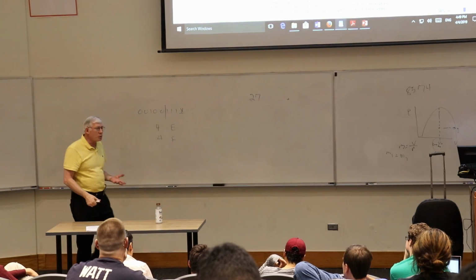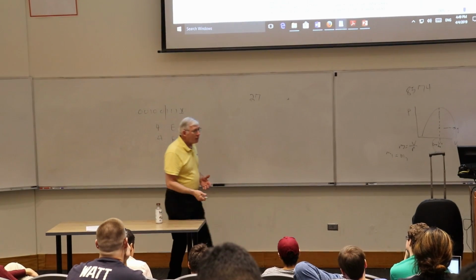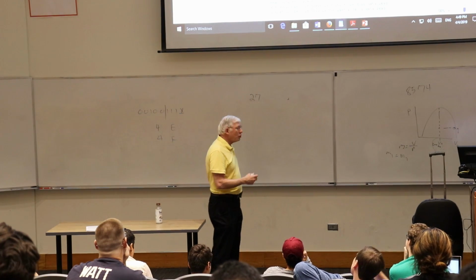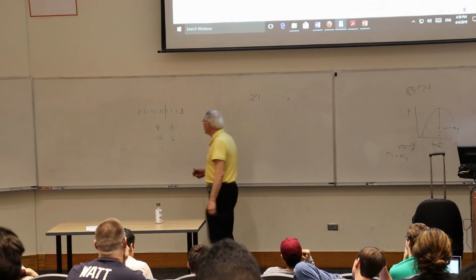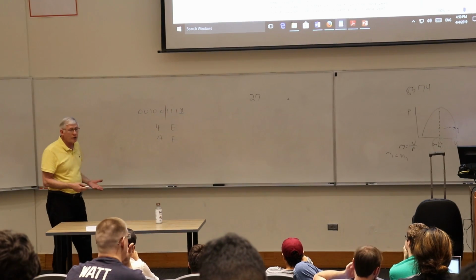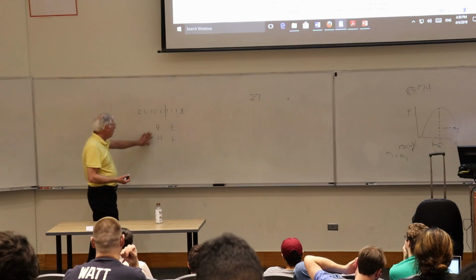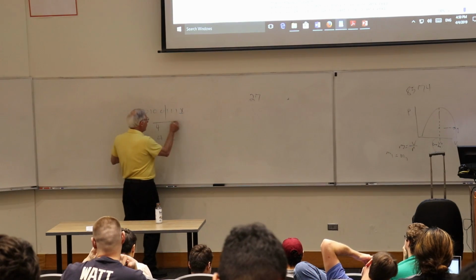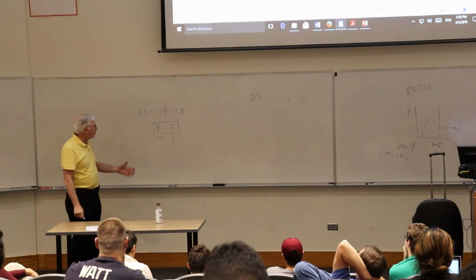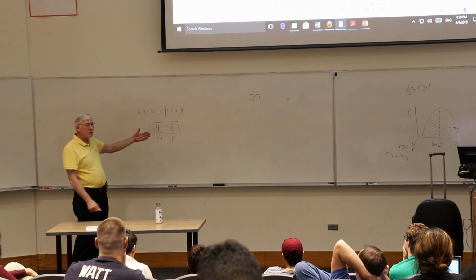So here's where the problem comes in. It would be fine if everybody used the same convention, but everybody doesn't. So when you read the data sheet, sometimes they'll tell you, let's say you have a device that you only read, you never write to it except when you write the slave address. So they might tell you, well, you should always use 4E. Well, are you supposed to shift that and append the read-write bit?